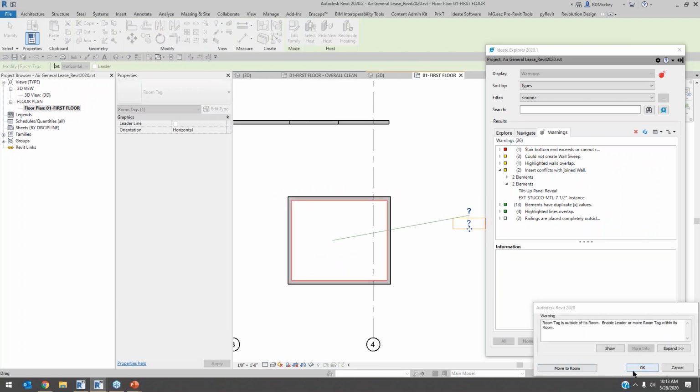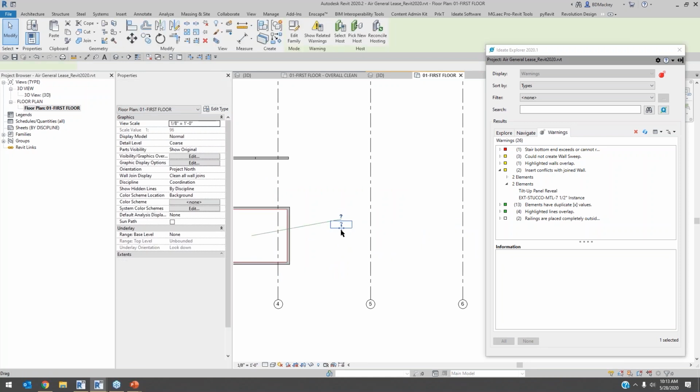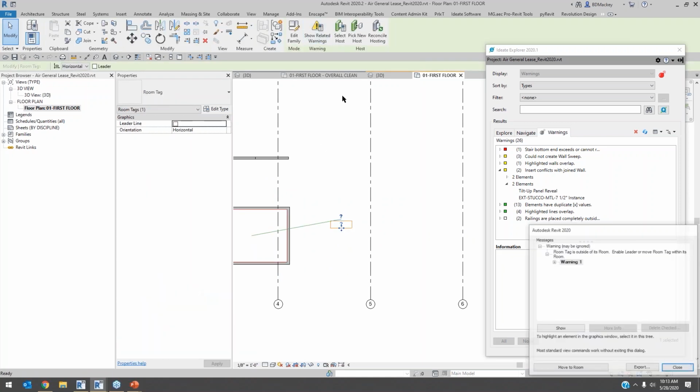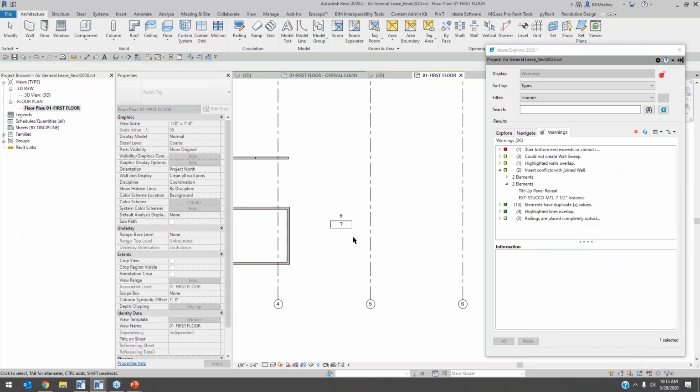This is going to give me a warning, and I'm going to say, okay. But what's great about this is if you select this and you say show related warnings, this is one of the ones where you get an option to fix that warning. Walls being attached to target, you could just say detach from target. There's a lot of different ones like that.